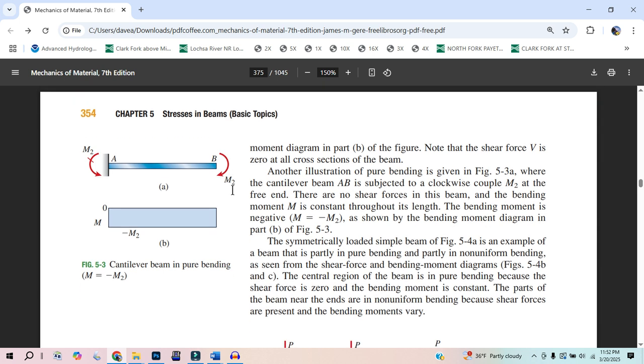We talked about that in detail in the last video. Do a free body diagram. Always take this thing and put it into outer space. I'm going to put it right here, but pretend it's floating in outer space. Right here, I'm going to put a downward force and an upward force, and this moment is going to cause the beam to rotate if it's just floating there in outer space. But we come back to Earth and we see that this thing is static, it's not moving. So we go back to outer space, and there must be something that keeps it from moving.